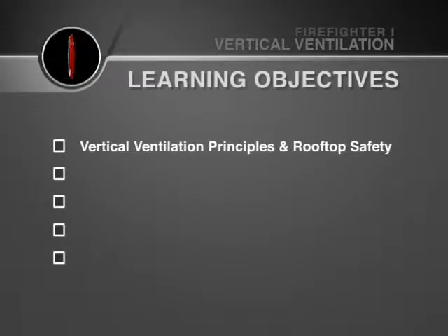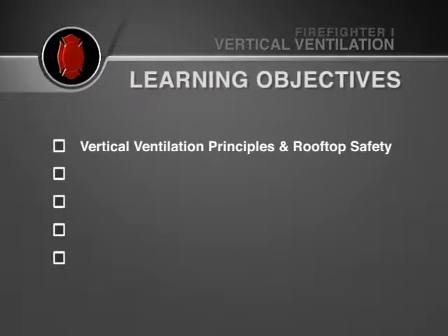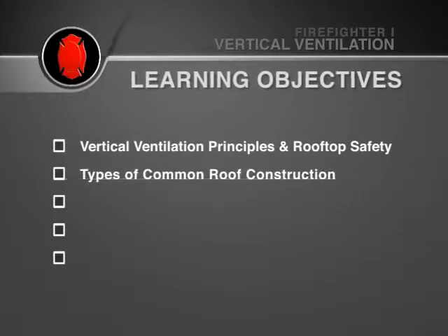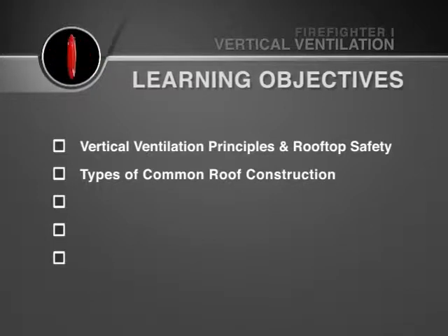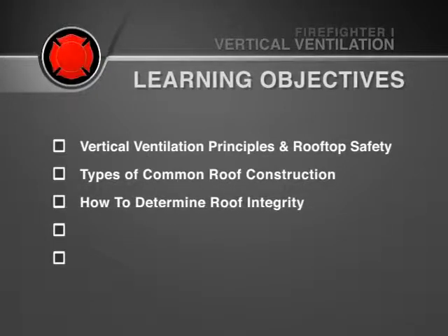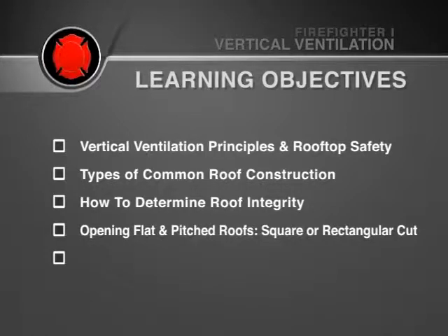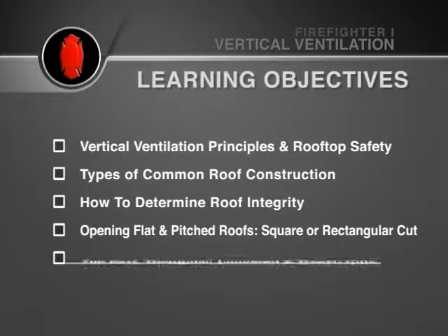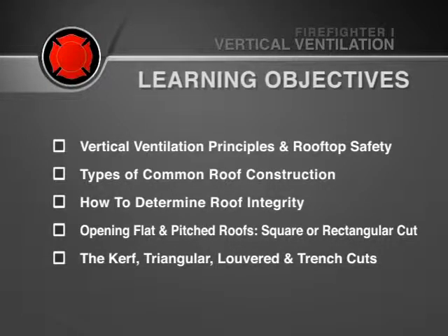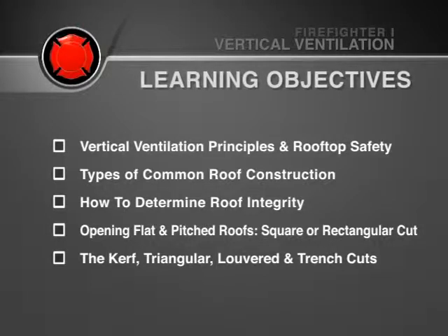The learning objectives are to define the principles of vertical ventilation and general safety precautions for rooftop operations, to present common roof types and roof construction and their role in vertical ventilation, to show how to determine the integrity of a roof system, to demonstrate how to open flat and pitched roofs using a square or rectangular cut, and to demonstrate the kerf cut, triangular cut, louvered cut, and trench cut.